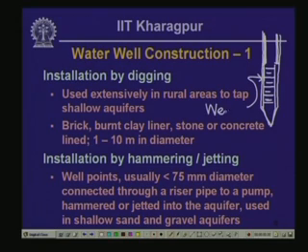So this one here is the cross section of our well point. This particular assembly is hammered into the ground, or it can be installed into the ground by jetting water at high pressure through the perforations. Usually well points are less than 75 millimeter or 3 inches in diameter, and this particular method is very common especially in North America for installing residential water wells within shallow sand and gravel aquifers.